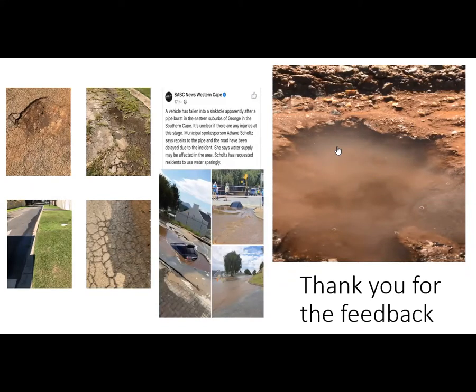And as you know, water is treated, so you have chemicals in it, chlorine, that kind of stuff. And being in a dolomite area, this will definitely become a bigger and bigger hole or doline, and eventually possibly turn into a sinkhole. So these things need to be attended to quickly. They need to be repaired. We need to look after our infrastructure, and we definitely need to attend to these things. So if you come across something like this, or if you're a consumer listening, make sure that you report this to your local authority.